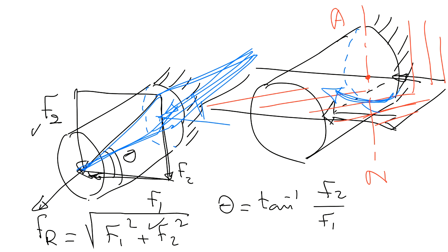Doctor, I have a question. When we were doing the mechanics of material course, we took two neutral axes, for both cases we calculated, and then we joined the values. I'm confused about that. If you are talking about the total, there is only one neutral axis, by the way. You did not get the meaning of the neutral axis, Muhammad. If you remember this stack of paper, and I let it bend down under the effect of the force, I told you that the upper layer gets stretched and the lower layer gets contracted, and there is a layer in between that did not suffer from anything.